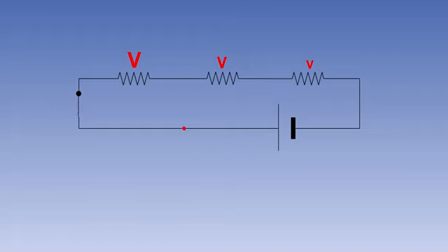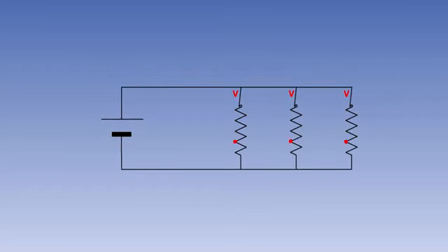Series connection of loads is impractical, because individual resistive loads cannot be individually controlled. Also, the failure of one resistor would mean failure of the rest of the circuit. Parallel connection ensures each resistive load is individually controllable and receives the same voltage. Failure of one resistor will not affect the operation of the others. Most aircraft loads are connected in parallel.